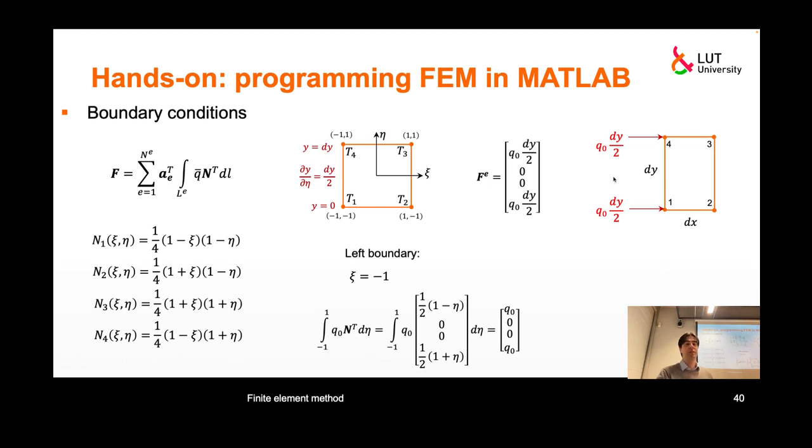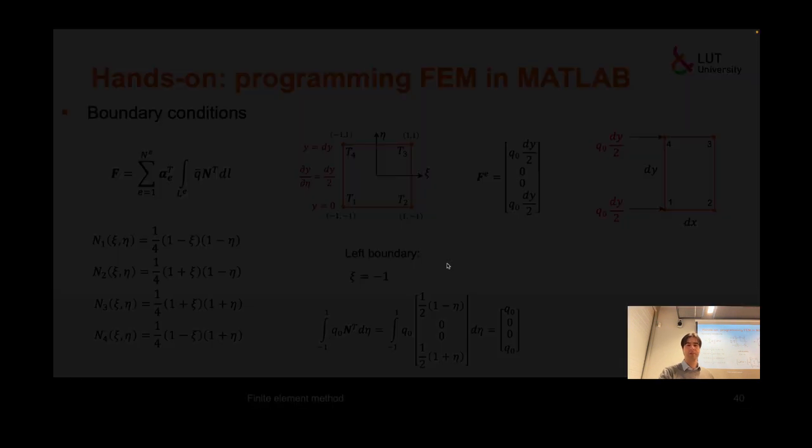And that results in not equal values of heat flux. It's not just divided by 3, it's different in quadratic case. But in linear case, it's as simple as that. But we also made it formally. Okay, this is how we are going to fill this right-hand side.